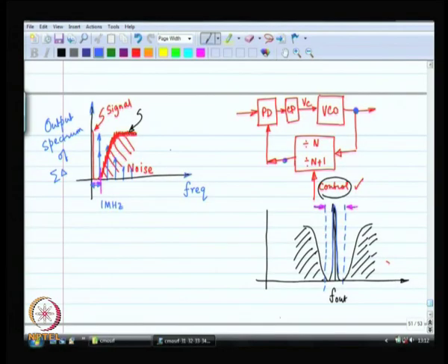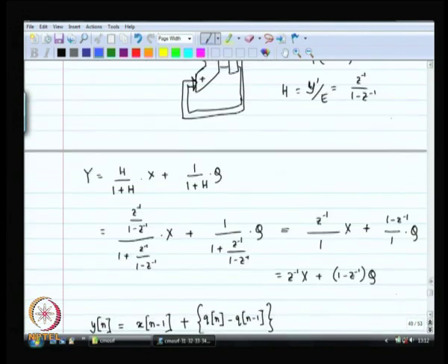The sigma delta design has to be clean enough, nice enough and robust enough that you do not add additional noise. As a result, your simple addition circuit over here is definitely not going to work, you will have to work harder, you will have to place zeros, you will have to burn more power in your digital circuitry. This is digital, all digital, right. There are no analog signals in the sigma delta over there.